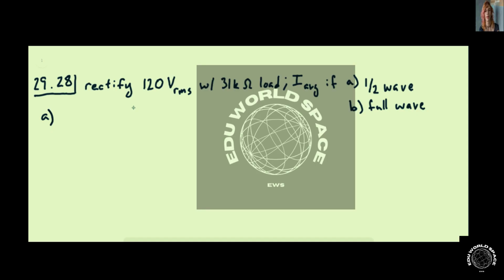So if we have a half wave rectifier, then the current is going to be zero half of the time. That's sort of their distinguishing characteristic. And so we're going to approximate the average current as being the appropriate fraction of the full RMS current, which, since it's positive because of the rectifier, should work out pretty well for us.